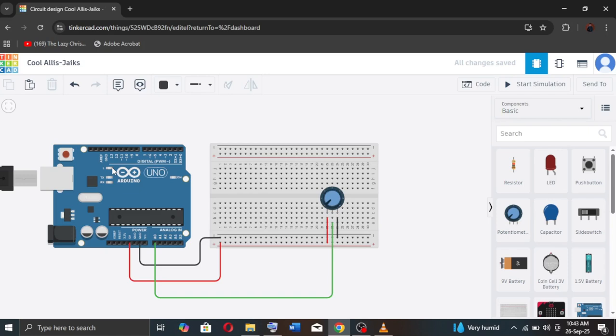So, in most cases, when we want to read an analog device like a potentiometer, we will have to use the analog inputs. Now, let's recall that we work with both digital and analog devices, like motors and the rest. So, how are we able to work with them efficiently? If you're working with a DC motor, you might want to increase or decrease the speed. But because of the nature of the Arduino Uno, or the Arduino boards that we're using, you can't really do it that straightforwardly.